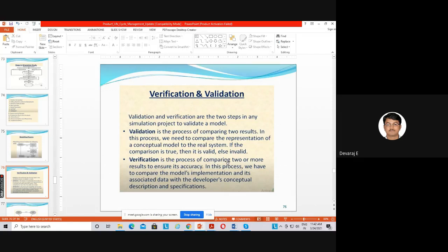So if defects are more, then automatically we can say the material is going to fail. So we should check the results between these two, whether your numerical method as well as the experimental is giving the same results or not, or at least similar. Okay, if it is not similar, then we should check the design, that is the first process, whether the design of the mathematical model, that is the design in ANSYS, as well as the practical design, is the same or not.